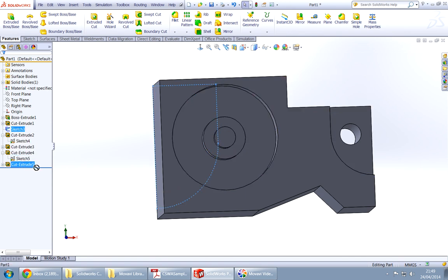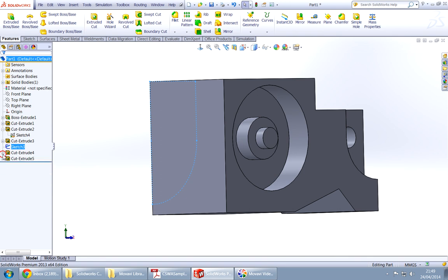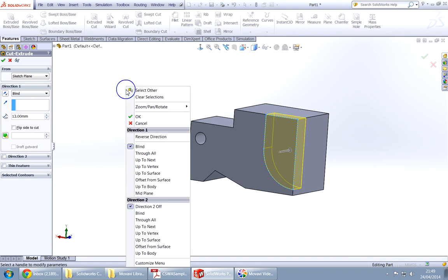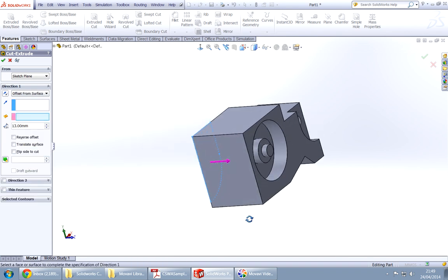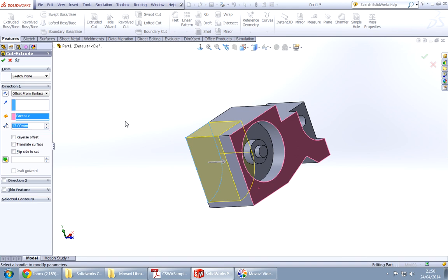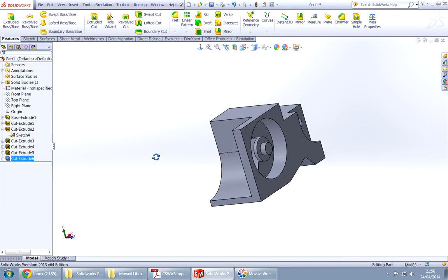So we bring the sketch down to the bottom of this. Why doesn't it let? Okay, should be right here, hopefully. No, why doesn't it let? So choose this sketch, press D, since everything's okay. Offset from surface, how much? It was 8. Choose this surface, 8, double click, and we're going to here.